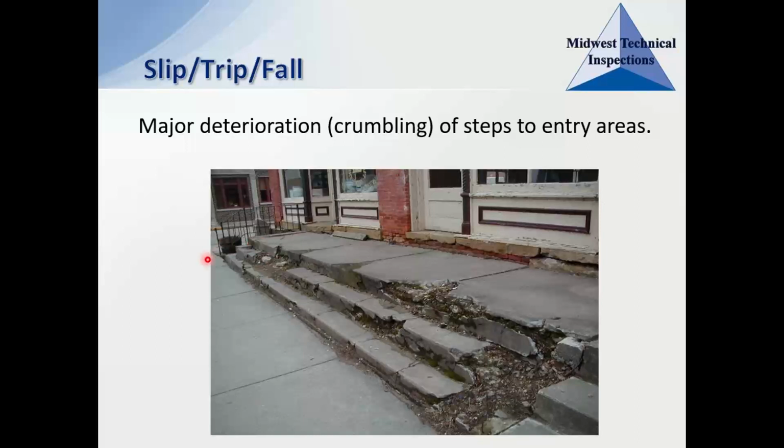What we do see sometimes is the horizontal barriers. So they may have like a 2x4 going across here or something like that. That is not considered acceptable because it actually encourages climbing. So like they would encourage a kid to climb up onto that and maybe climb over the railing or so on. So we want to see the vertical spindles in our guardrails.